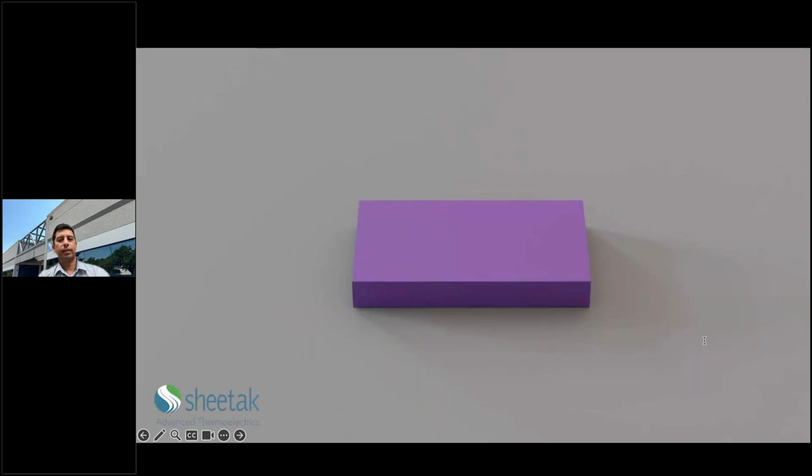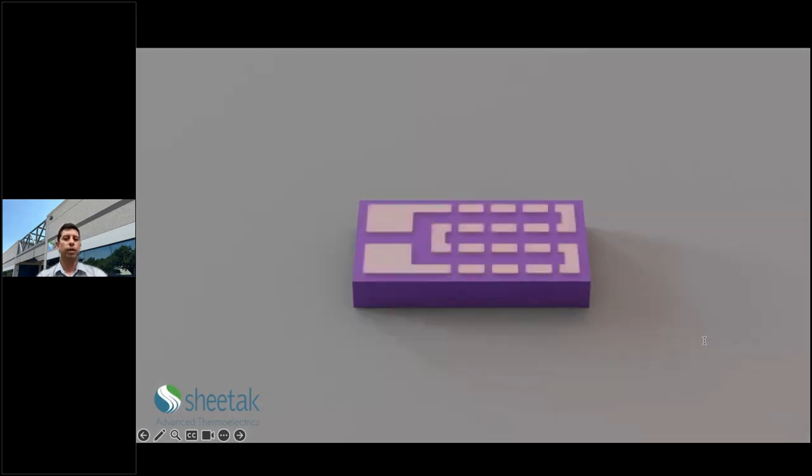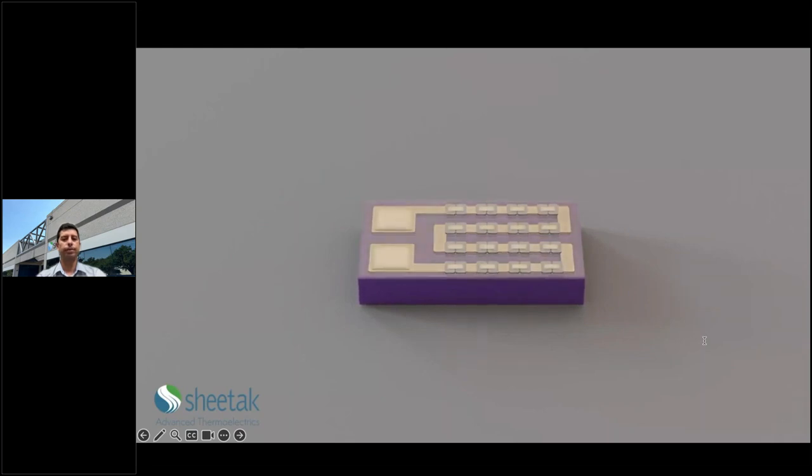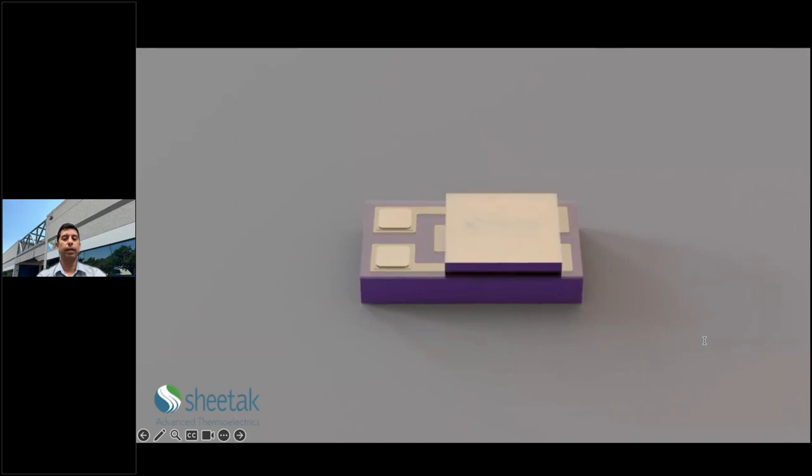Our thin film device is built using advanced semiconductor techniques, like wafer scale processes with high precision, and is highly automated. We start with a silicon substrate. We deposit the metal interconnects, TE materials, and barrier metals directly onto the wafer. The wafers are then diced into the final chips and used directly or assembled into our required combinations. This is solder-free precision manufacturing, and the elements remain hermetically sealed. Optionally, we can add a top lid again for thermal spreading.